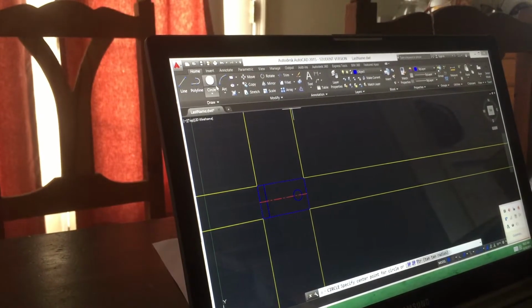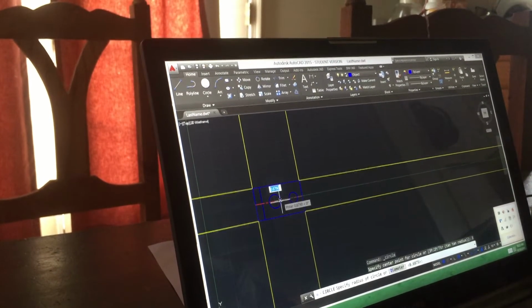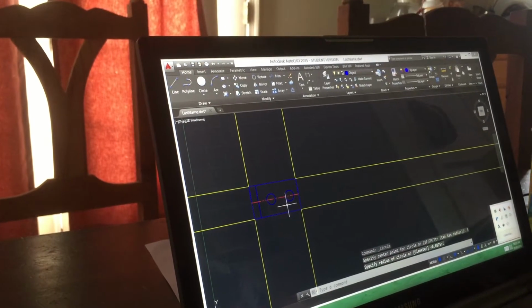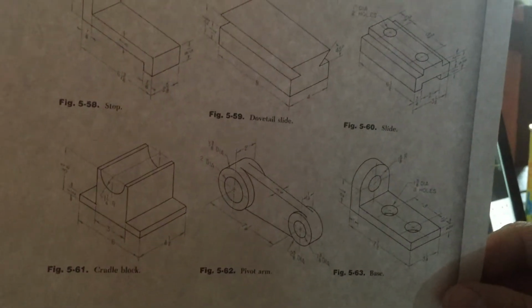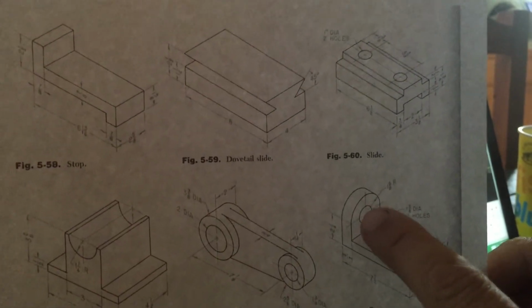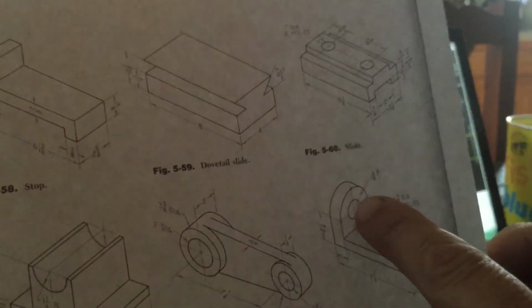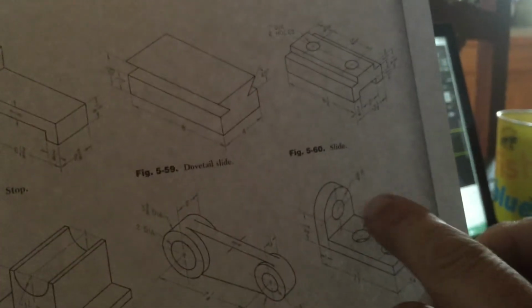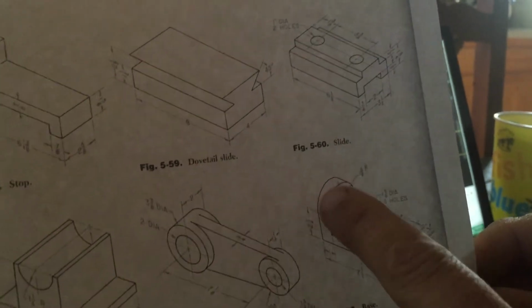And then I'll do a circle again, and I know it's back 3 inches. So I'll go from there, I'll go back 3, and that gives me my circle. I also know that there is a circle here with the radius of 1 5/8 inches. So I'm going to use that center line, and I'll offset it 1/2 of 1 5. No, I'm sorry. That circle is 1 3/8 inches. So I'll just bring a couple of lines back from the edge of these 2 circles back through that piece there. We know they'll be hidden.